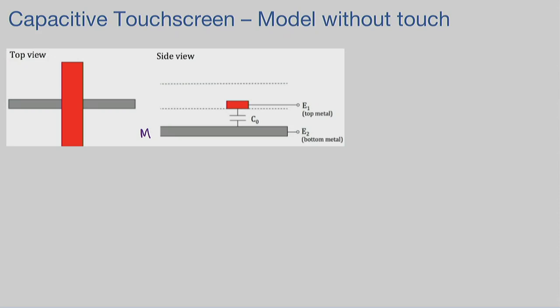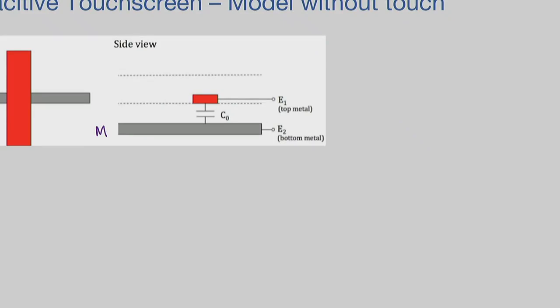Then you go and deposit a material that is a dielectric. So let me color our dielectric here, pink. You deposit a material on top of those metal lines, and you know that this material is an insulator, does not conduct current in that direction, right? It isolates the conductor that was patterned on the bottom. You're making a sandwich, a stack.